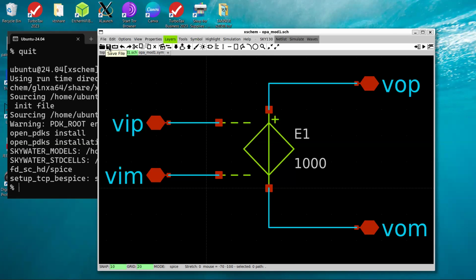So let's say you have a very complicated schematic and you have two input ports, two output ports. You have to put these pins, and that pin you get from, where did I get it from? Symbol, right? No, sorry, you do get it from the devices library. From your devices library, there is input.sim, there is output.sim. Do IO. For when you're doing analog circuits, we don't use input. In digital circuits, we'll use input and output because then you can figure out if you're shorting two outputs or not. But in analog, there is no shorting the output. It's just an analog pin. So in analog, I'll always keep it as IO pins. That way you're not getting all the stupid errors and warnings.